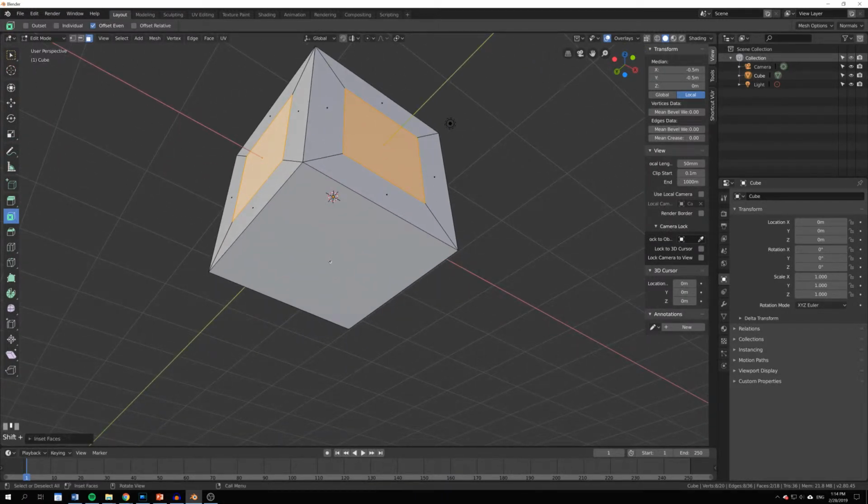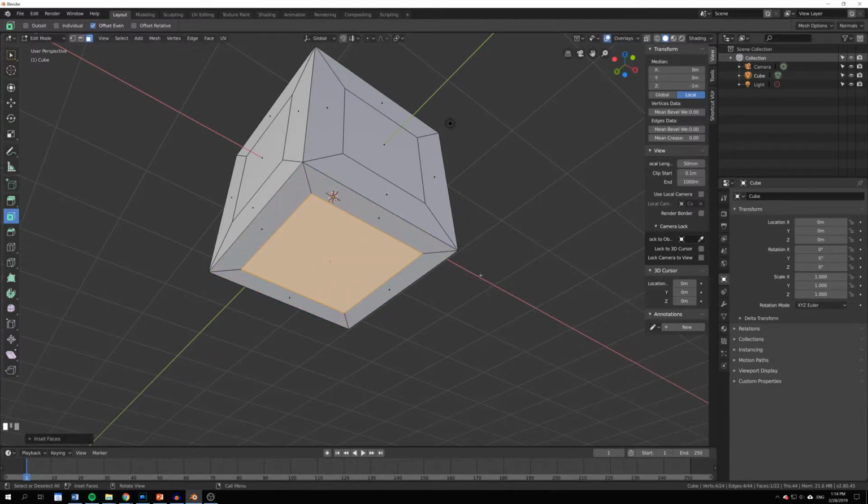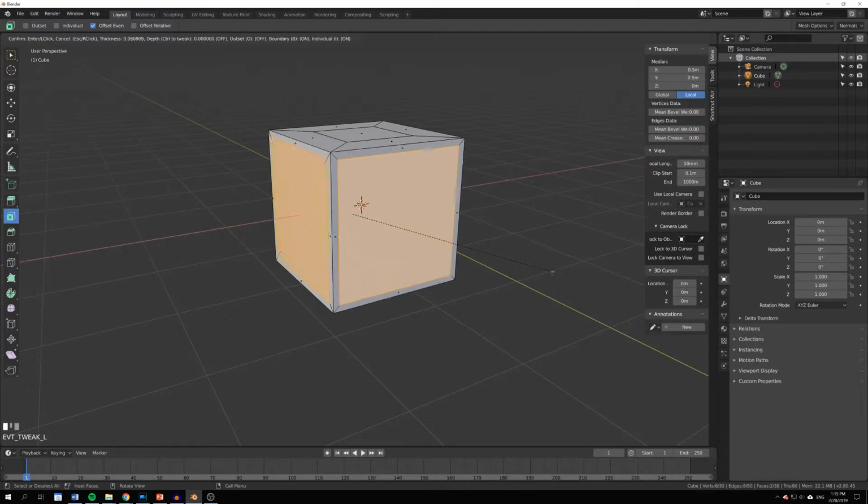other functions are available. So I'll just select this face and click and hold and start dragging, and you see just above where it says user perspective up here, there is a row of additional tools that we use. So when I'm still holding the key, when individual is on, every individual face will be inset by itself like we did before. Now I only have one face here inset, so I'm just going to release that and go back here, select these two, press and hold, and press I while I'm still holding to switch between individual and combined.